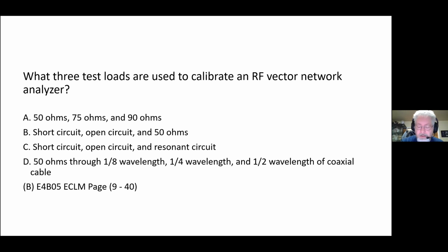So what would 75 ohms indicate in your SWR meter? 75 ohms, is that the open? No, it's not open because it's 75 ohms. Oh, that's right. I actually use four of them: open, short, 50, and 75, to make sure my meter is stable over its entire range.